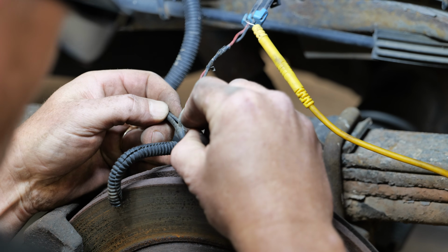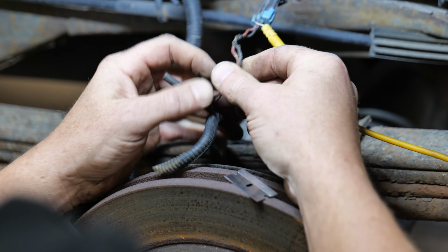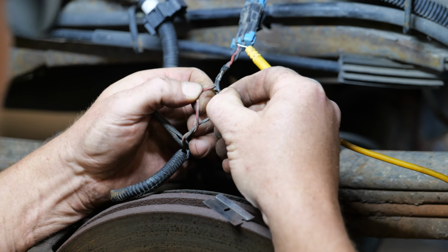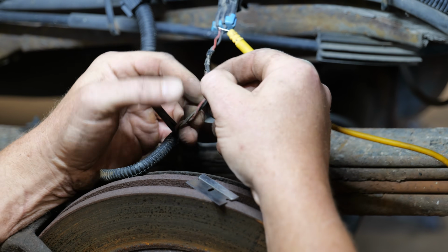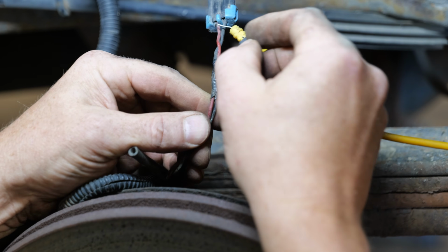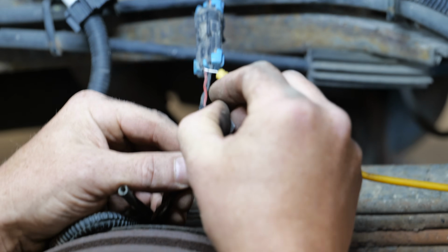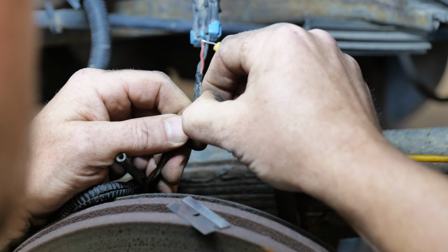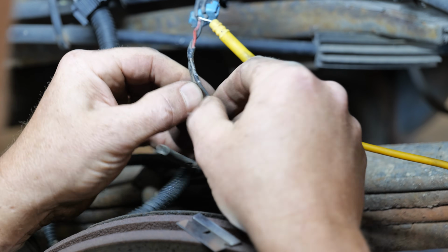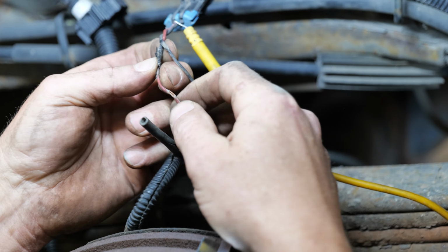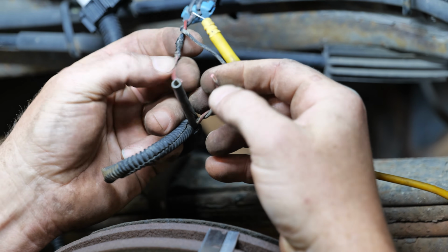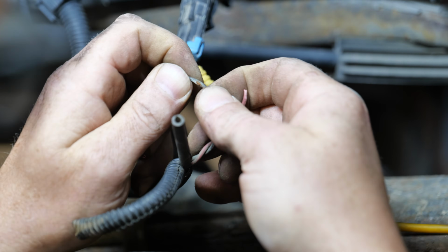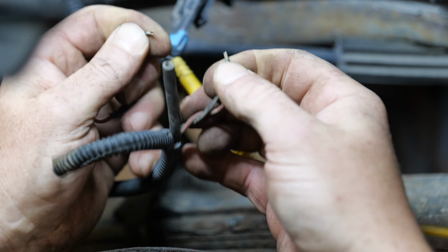Crazy that there were no rub marks at all from where that was. I should have focused a little bit more on that. You typically don't see that kind of rub-through unless it's rubbing on something. So we've repaired ABS wires before, and this is an area where you have to be cautious about how you're repairing it because of vibrations, which is really what caused this in the first place. You're going to see it up right there. Just pulled it apart. And then the ground wire, like I said, is not completely broken. I should be able to pull that one apart too.